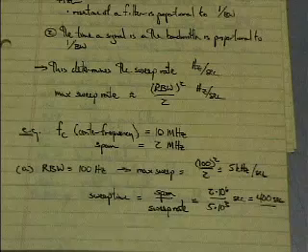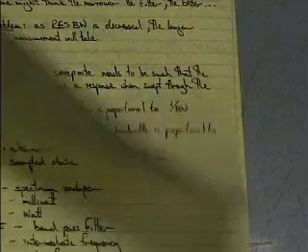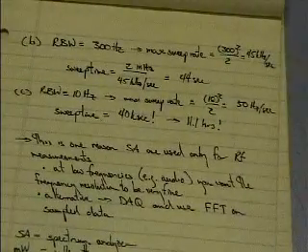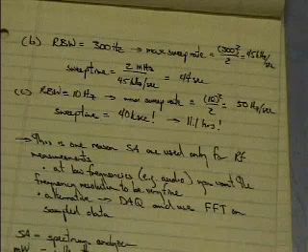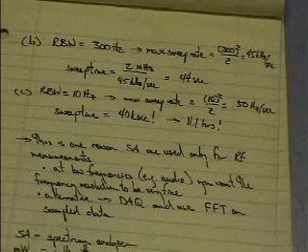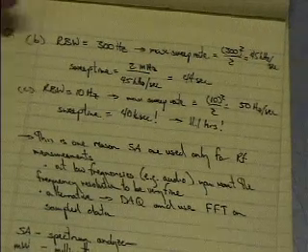All right, so what we'd like to do is increase the res bandwidth. Well, the downside of that is it's going to let in more noise in our measurement, and I will no longer be able to distinguish two signals that are, say, 110 hertz from each other. They're now going to have to be over 300 hertz from each other. Well, that may or may not be a problem depending on your signal.